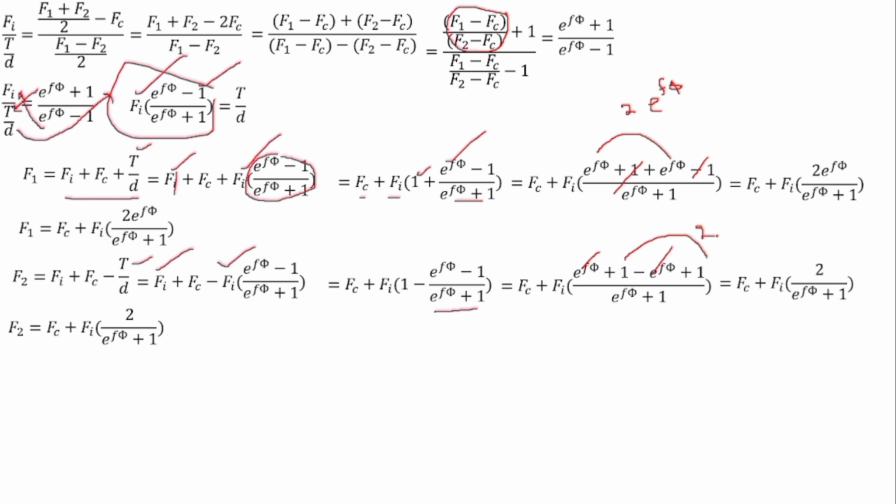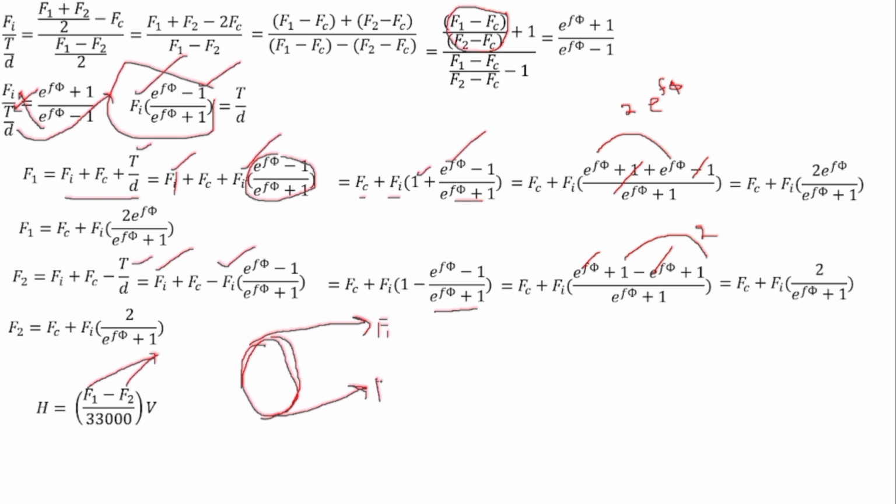So these are the formulas that will be used to analyze the belt, or these formulas will be used in the design as well. And the power that will be transferred can be calculated by this equation. Here, I just want to make one point. Let's say you have this pulley and there is a belt wrapped around it. Now, if you exert equal forces on both the ends, you will not be able to rotate this pulley. Power will not be transferred.